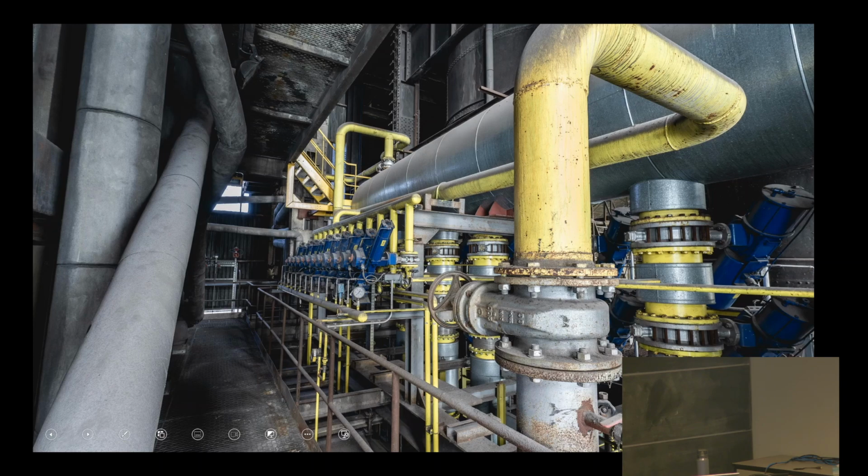Say you have to maintain this equipment, you shut down all the pumps, the flow all slows down. This flow could be quite pressurized still. So if you close this gate valve and open this, you can let out some of that pressure. So it's not just a big source of stored energy. Say we have to replace this valve, we could use this to basically bleed off some of that stored energy before we start undoing these.